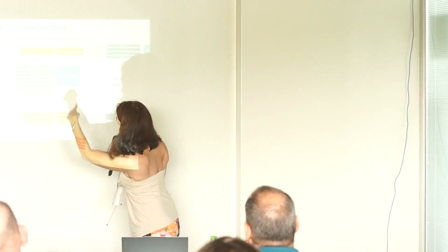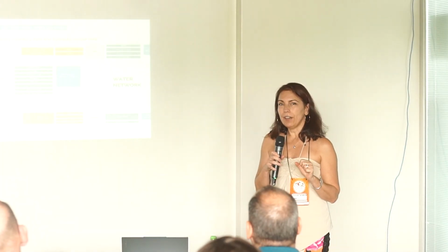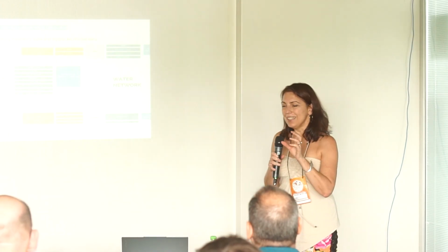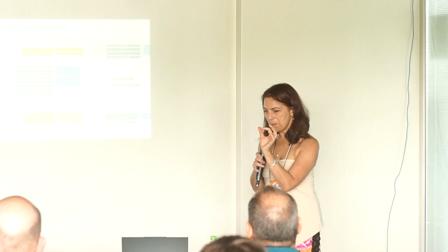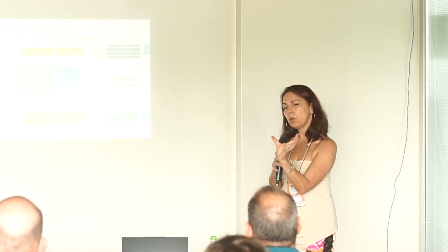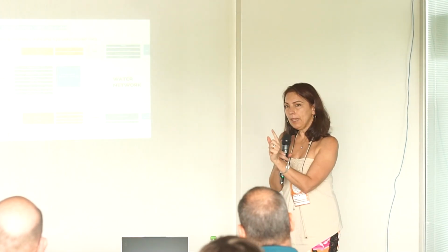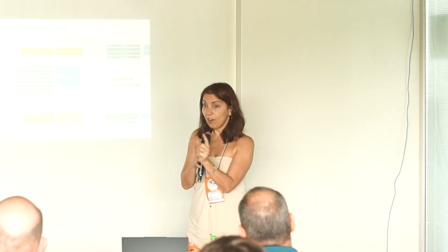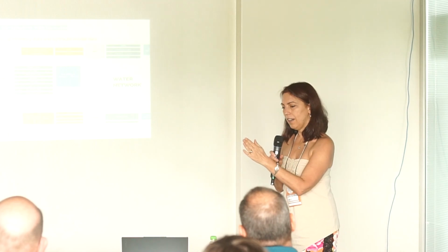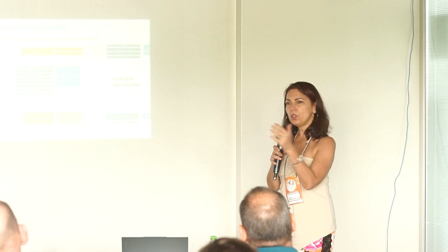Then, it's difficult to be seen here. Giswater came with a concept that is named inlet. So inlet is a node that, depending on the sectors that you bring in at the same time to simulate in Epanet, can be a reservoir or a tank. I mean, inlet is in fact a tank, but one that connects two sectors.